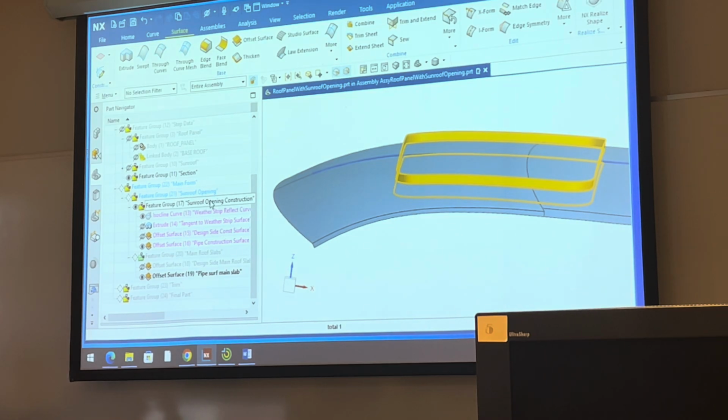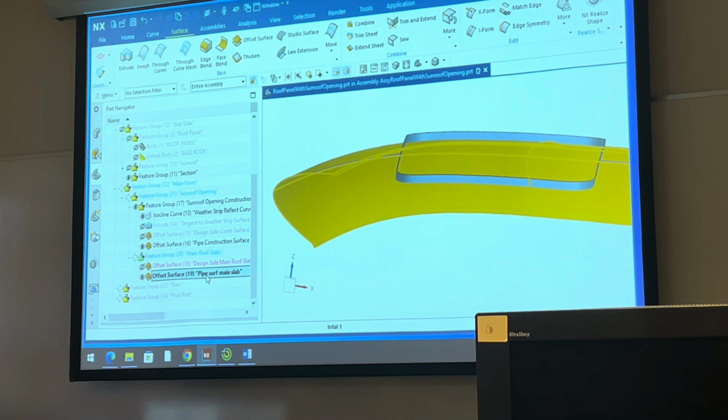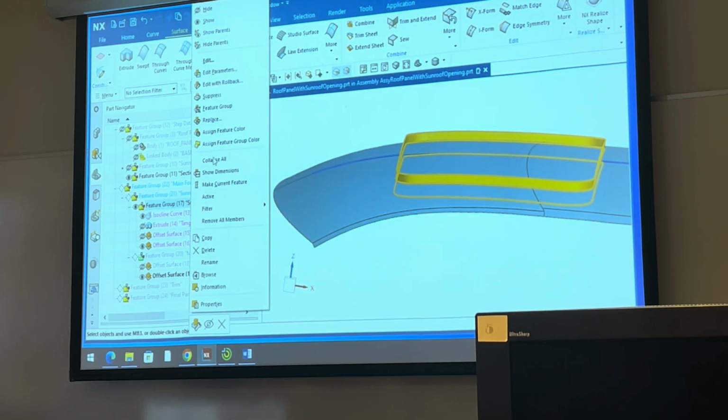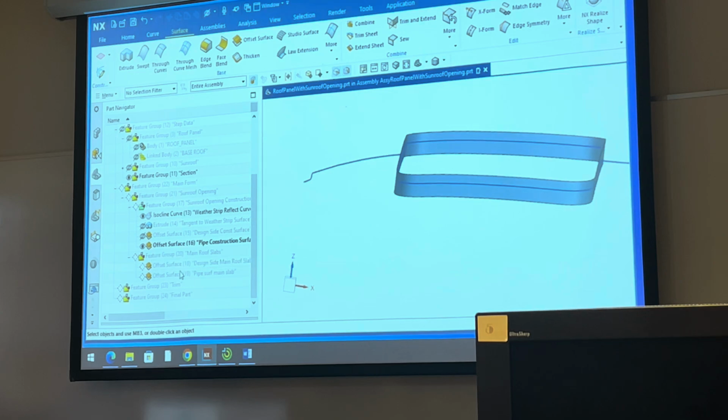The intersection curve that's the middle of that fillet. But I need it in here. It's an intersection between this guy and this guy. Well, if I want the intersection in here, if I make that active, I can't get to that guy because he comes after in the history. So, in other words, I need this to come before that in the history.